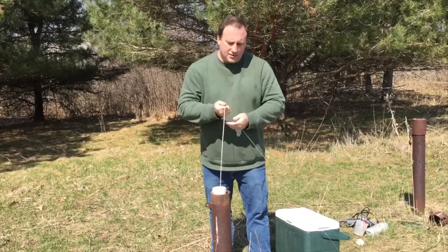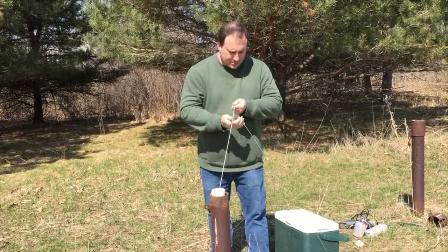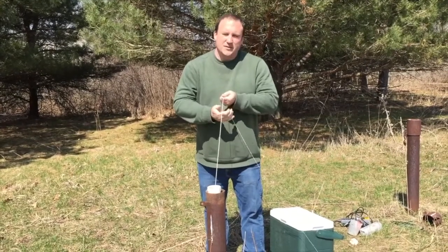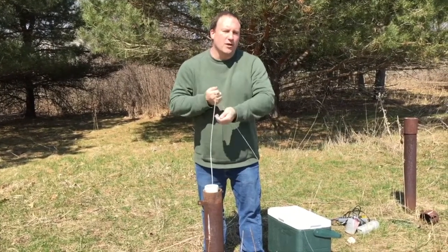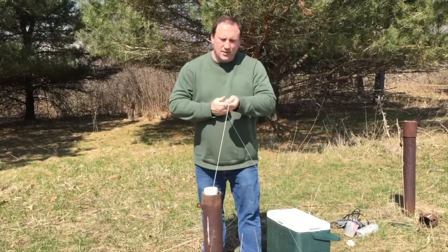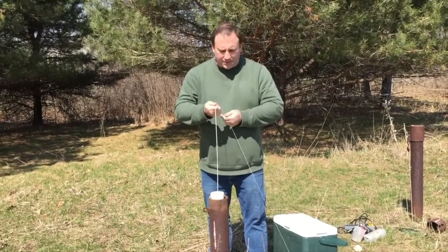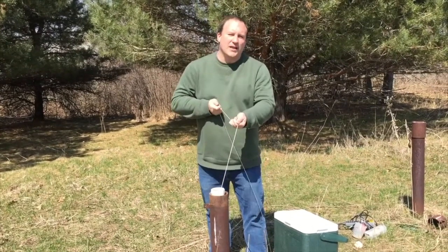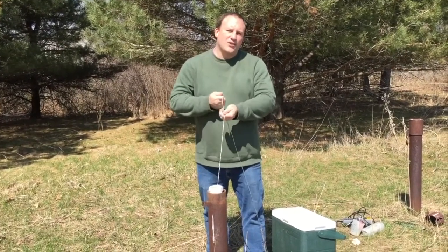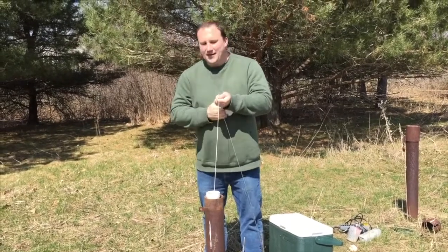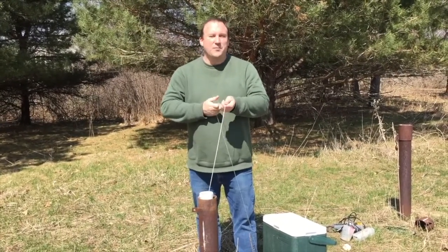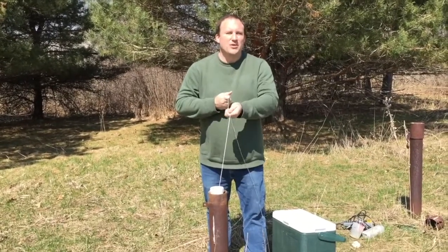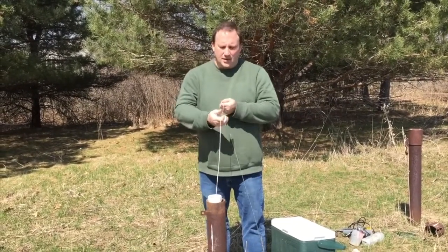I already pre-measured out at least 40 feet of rope in my driveway, so I kind of know where I'm going. Now there's a little bit of displacement that will take place when I lower this data logger into the well, but a pretty small amount. So I'm going to be able to wait 5 minutes or something. By the time I get this all tied up and get everything ready to go, that should have dissipated. Ideally, I would take another water level indicator and make sure that that has happened. But in this case, I'm showing you the demonstration, and I'm going to probably give you some other data.